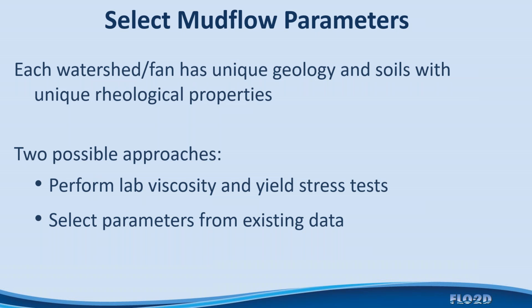If you can estimate what the shear rate should be by just taking a mean flow depth and estimating what the velocity is and plotting it as a linear rate of strain, then you can get the rate of strain value, and you'll see that it's on the order of a tenth of an inverse second, maybe up to a half or 1 inverse second. So I caution you if you're going to do that.